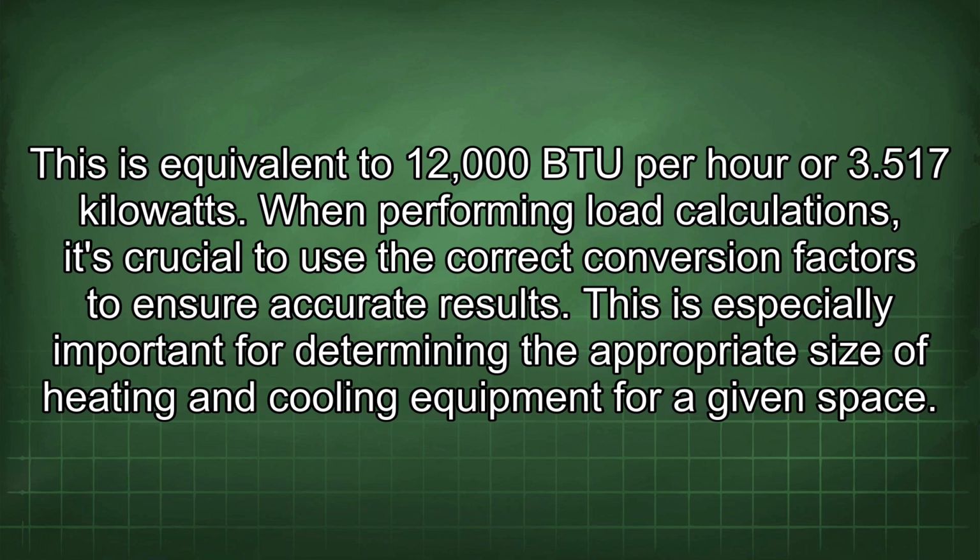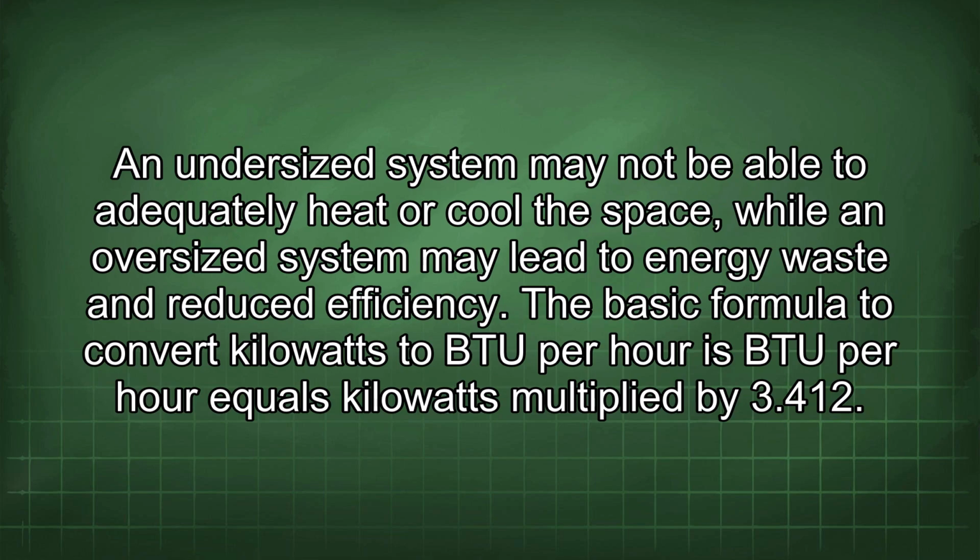When performing load calculations, it's crucial to use the correct conversion factors to ensure accurate results. This is especially important for determining the appropriate size of heating and cooling equipment for a given space. An undersized system may not be able to adequately heat or cool the space, while an oversized system may lead to energy waste and reduced efficiency.